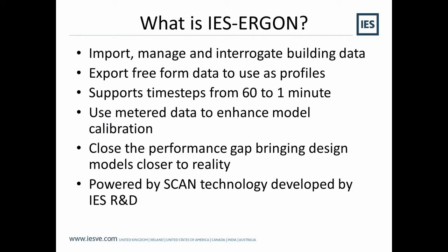If you do have 1 minute interval data from a data source on site, then we can import that. Probably looking there at maybe a SCADA system or a manufacturing facility, which might give you that 1 minute frequency data, whereas traditionally your typical building management system is probably going to be working more in the 15-minute resolution.